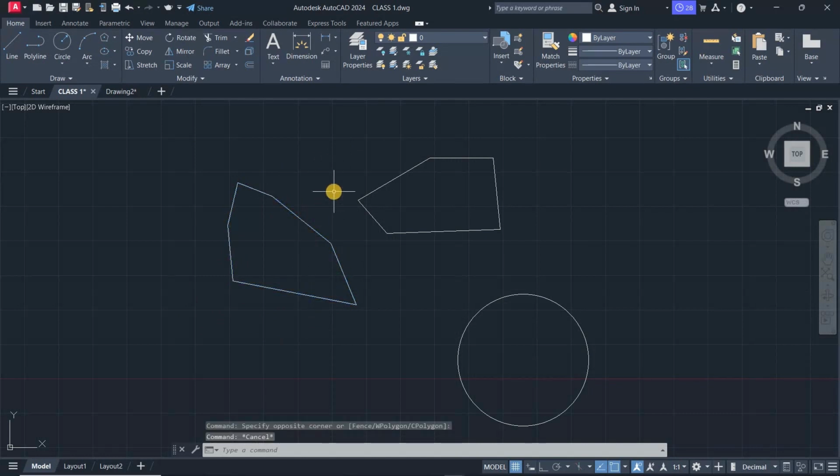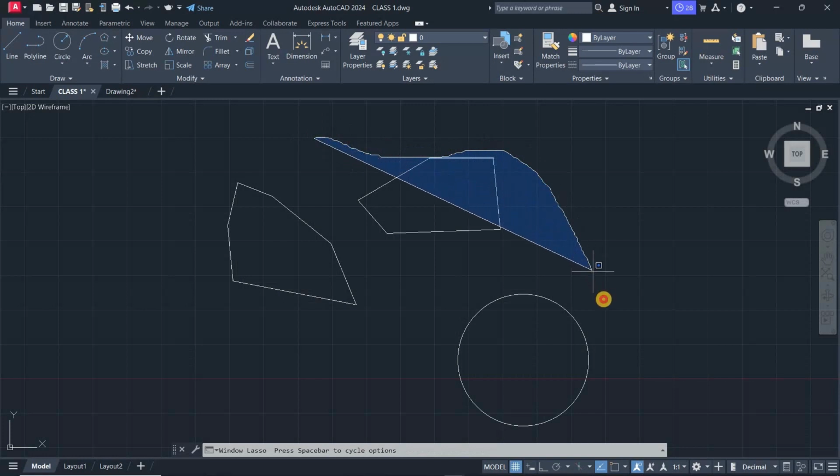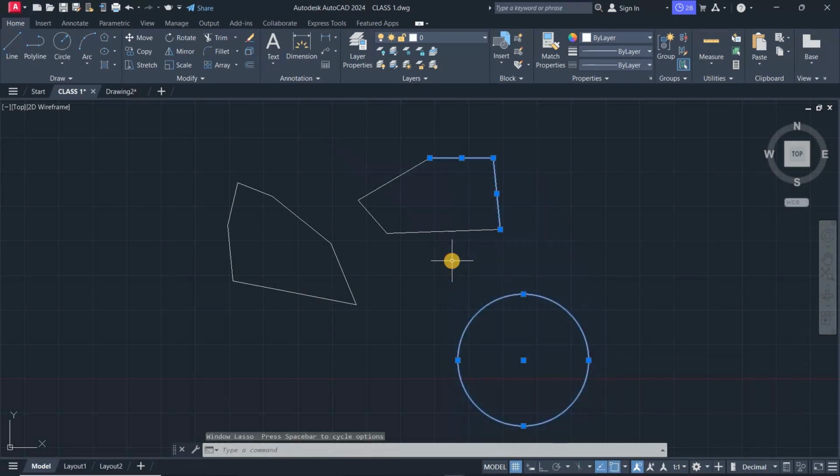There's also another selection called the marquee selection in some software, but in AutoCAD we call it lasso selection. So marquee selection or lasso selection, meaning if I click a point and hold down, I can define a range of objects manually that I want to select. So whether I want to use the solid window or the cross window, the solid window is what I'm doing now.